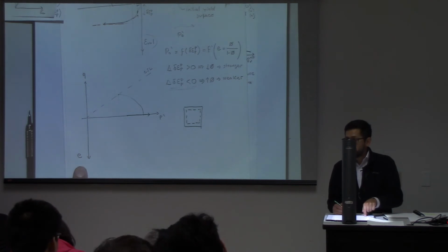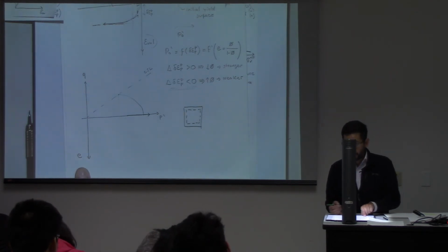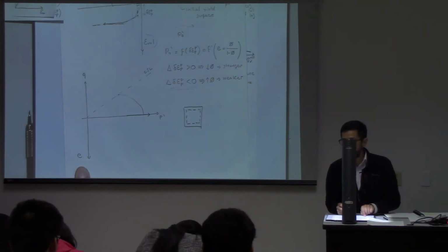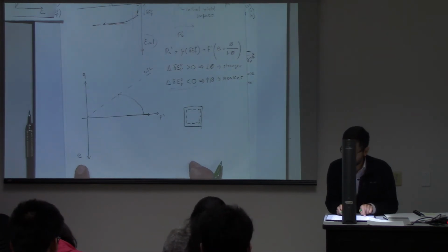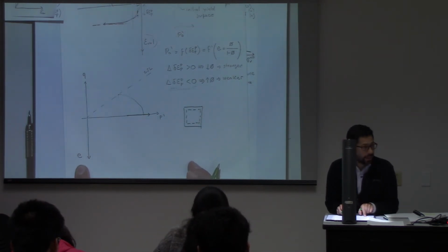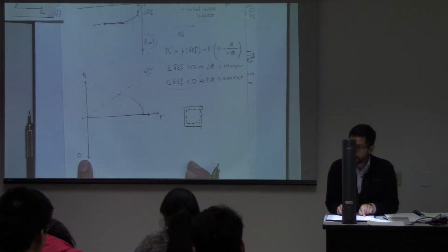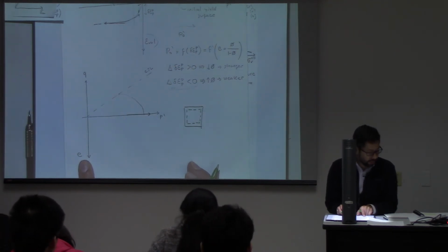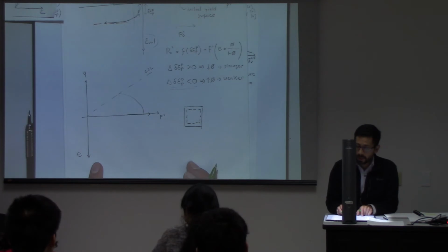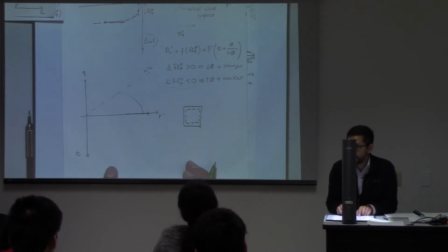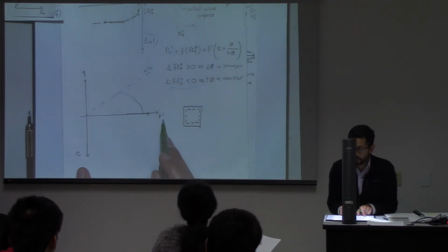It turns out that, as we explained before for the case of these clay sediments, the porosity, or what is equivalent, the void ratio of these materials, has a nonlinear relationship with stress.